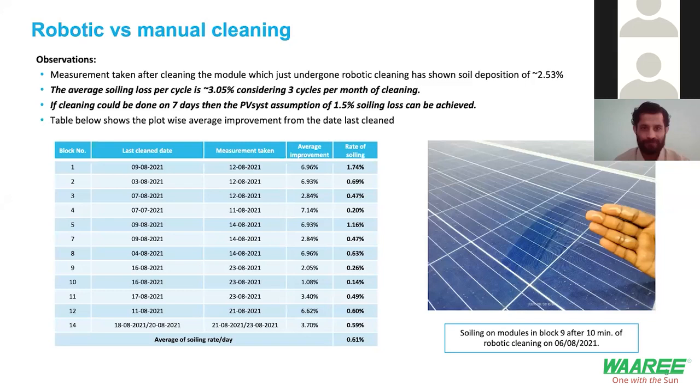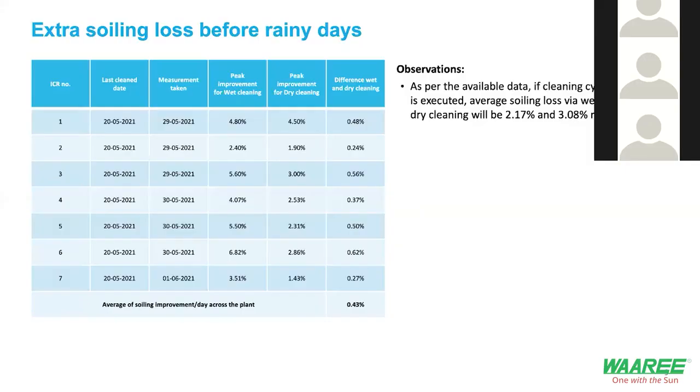So this is another thing. Again, with respect to soiling, this is another observation that we have made. As the industry grew, we learned a lot of things. Earlier the cleaning cycles used to be uniform across the year, but then we got more intelligent, and now the cleaning cycles are not uniform, they are skewed. During non-rainy months the cleaning cycles may be higher, during rainy months, lower.